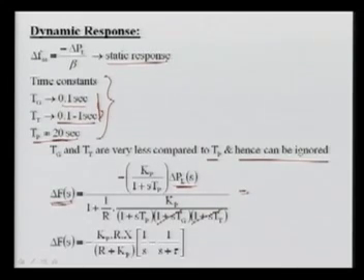and then we can simplify here, and what we are getting is GP over 1 plus GP by R, and then it is multiplied by your PL. So we can simplify from here and very easily get the dynamic response of the system, and this is your S here. Now I can say approximately this is the change in your Fs.